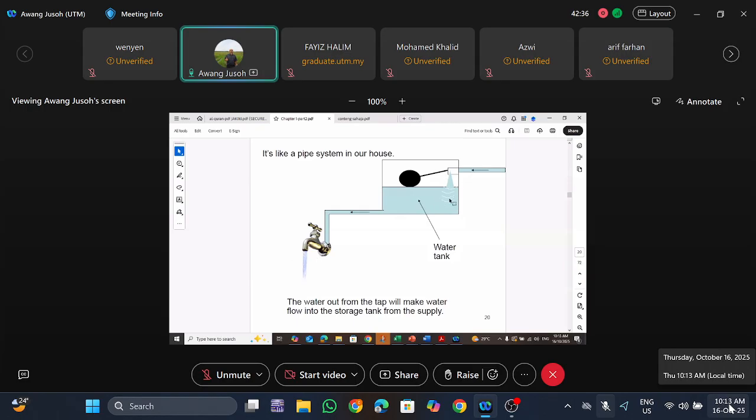During the process, there are some losses. We have losses in the electrical circuit, in the magnetic circuit, and also mechanical losses. Mechanical means losses in windage, friction and bearings. Magnetic means core loss. We studied before that we have losses from eddy current and hysteresis that make the magnetic core hot and so on. And the electrical system has loss in the wires. When current flows in the wires, we get I squared R, which represents the losses. The power input must be reduced by the losses first before you get the net power supplied to the magnetic circuit.